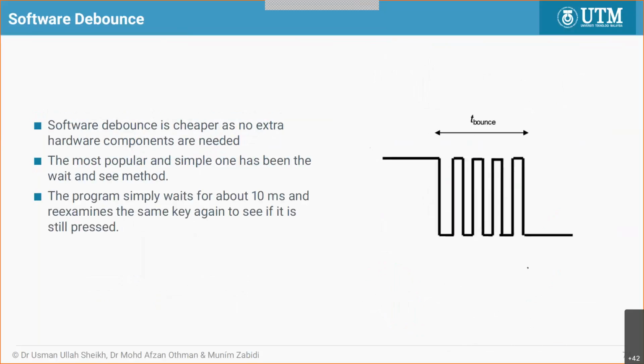Just read the pin. Read the pin. Is it high? If it's high, just keep on waiting. High, wait. 0, you delay. Delay for 10 milliseconds. Normally 10 milliseconds is a good value.